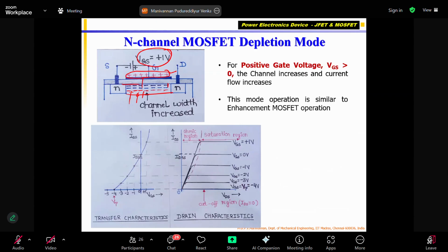So like this, you can vary. So you can see here, finally, I want to close this. You can see here, this is the input-output characteristic of the N-channel depletion mode MOSFET. I gave VGS equals 0, and there's a current going. It's not 0. When VGS is 0 in the enhancement mode MOSFET, ID was 0. But in case of depletion, you can see it's not 0. It may be something decided by the manufacturer. For example, 10 amps, 50 amps, depending upon the datasheet.